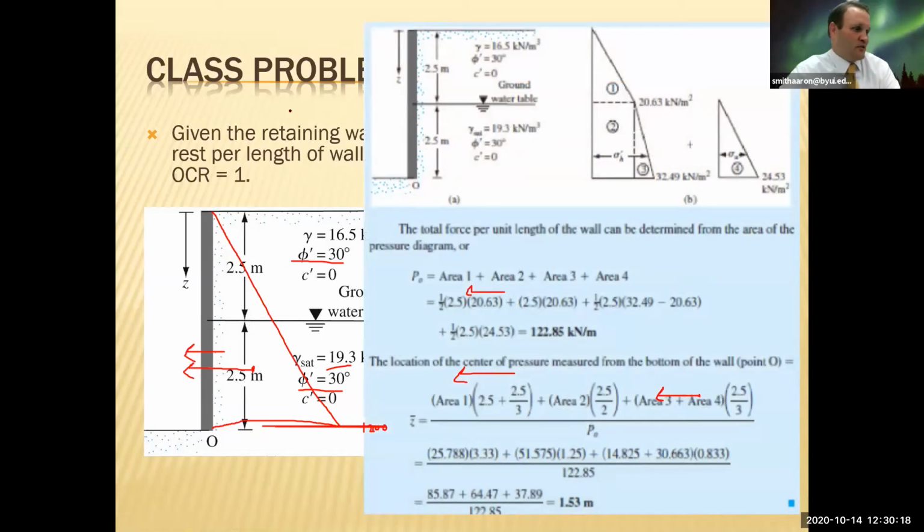This is kind of the solution I just want to throw on here, but I'm going to stop right here. But the forces that man felt when that trench collapsed can be calculated using these equations right here, and they're powerful. It's why walls fall over. Whenever you see an old retaining wall that's been in place for a while, usually the top's starting to tilt and lean over. The earth exerts a lot of lateral pressure. We've been mostly focused on that vertical pressure to figure out bearing capacity, but bearing capacity has this horizontal component that we'll start exploring over these next two classes.